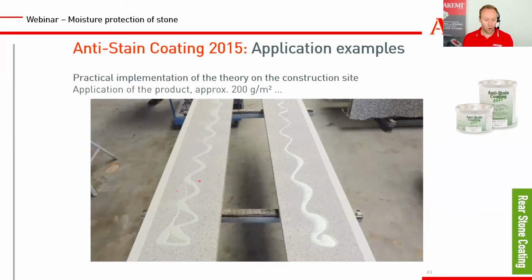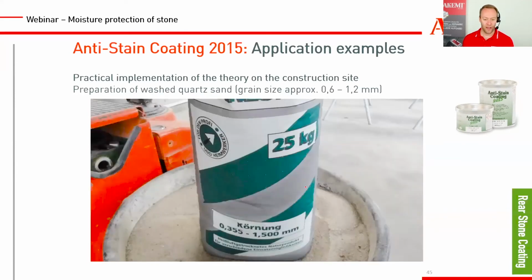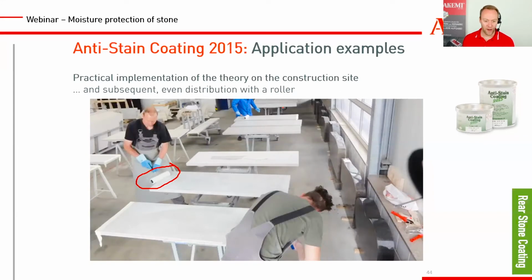And here, now you have again 20-30 minutes, because it's sitting here, temperature is normal, 30 degrees, 25 degrees maybe in German summertime. India, of course, is a little bit different. But then you have the time to spread it. And this is what they do. They have 1-2 people spreading, and one is mixing and applying the coating always. So here you can also see bigger slabs, bigger roller. And they were very fast, spreading the product in a very efficient way.